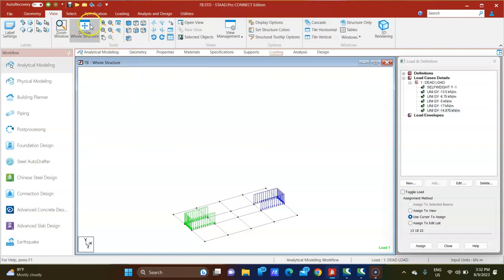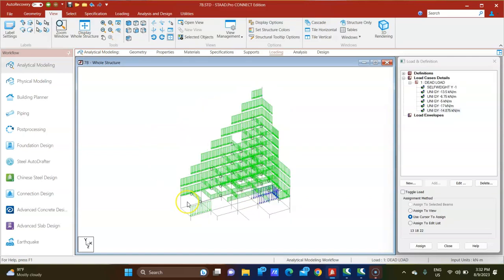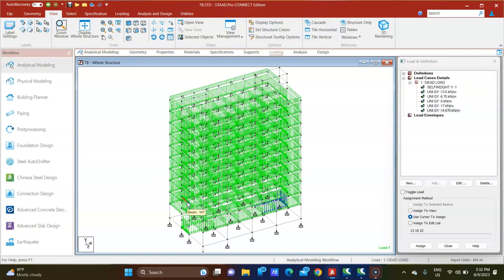Okay, so now if you see the whole body, your loading diagram looks like this, right? It means that whatever possible dead loads are there, you have considered all. We have assigned the load on three sides of the lift block. The reason is that three sides will be solid, one side will be free for the person to enter. Right? Similarly, same case with your stair also. One side will be open, na? Otherwise, how will the person enter? Clear? Everybody? Now tell me.